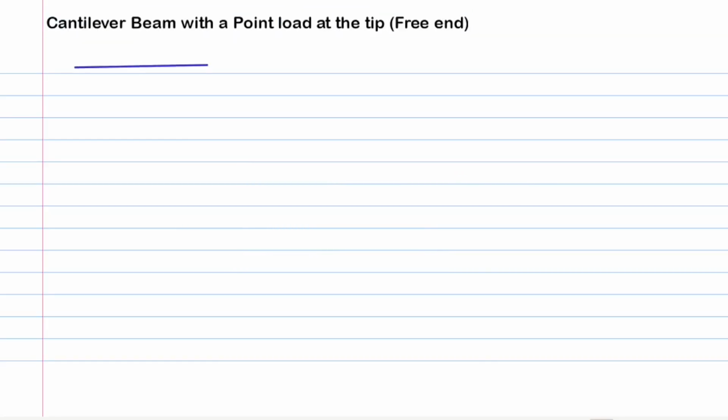Let's start off with a cantilever beam loaded by a point load P at the free end. Let us show the reference coordinate from where the distance x of the section is measured at the fixed support. We may first need to find the reaction force and reaction moment at the fixed end for writing the moment expression at any arbitrary cross-section along the beam's length.